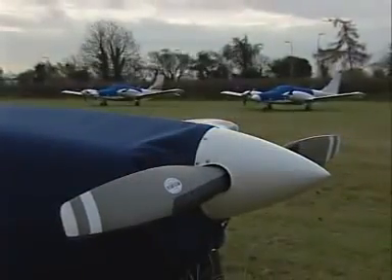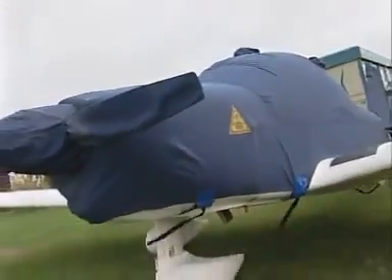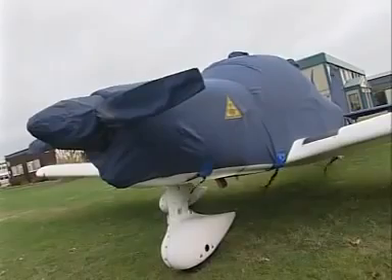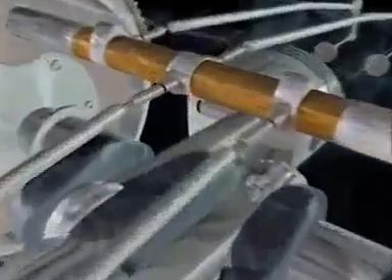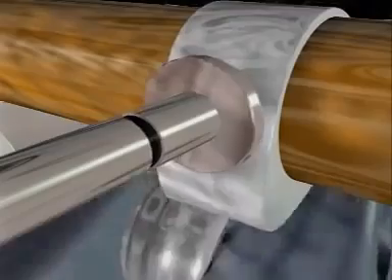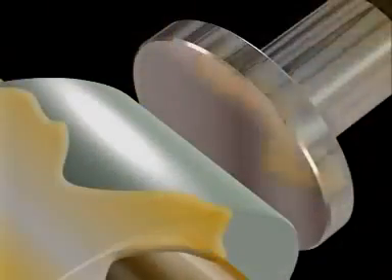If an aircraft is not used frequently, as is typical with private flyers, then elements can become dry. A lack of oil when the engine is first started can lead to metal-on-metal contact between the cam and follower, which can damage both. With infrequently used engines, additives can help.